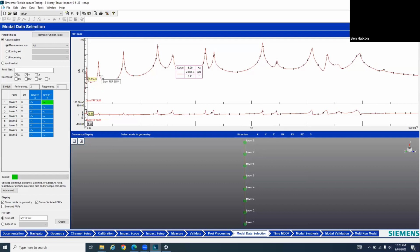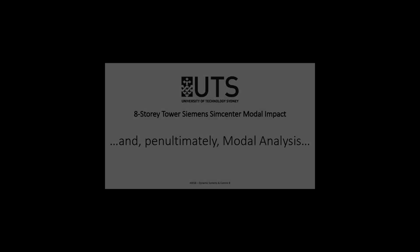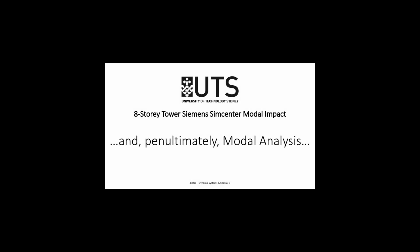That's the peak, 4 Hertz for the first peak, 25.5 Hertz for the second peak, 70.5 Hertz for the third resonant frequency, 131.5 Hertz, and so on. The first thing I can do with this FRF data is compare the frequencies with those that I've predicted from my simulation. But I want to do more than that.